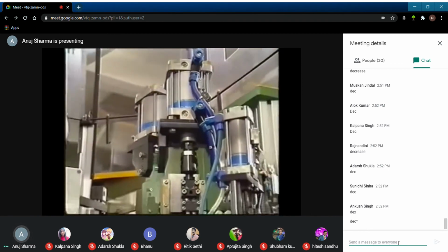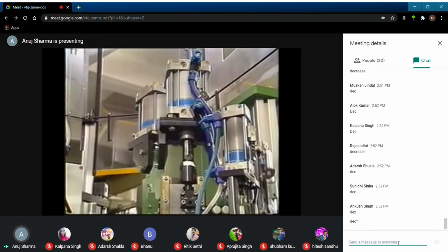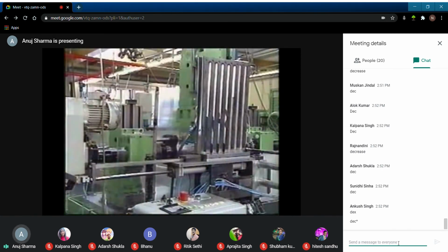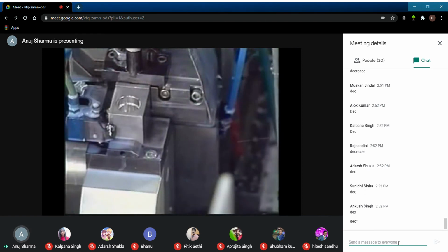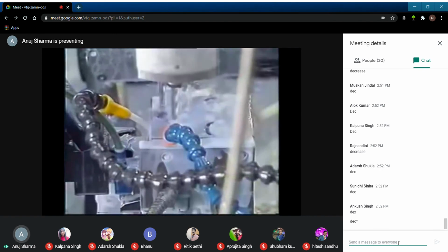The diameter of the piston directly affects the force, speed, and air consumption of the cylinder. The most efficient design uses the smallest cylinder adequate for the application. In this machine, various size pistons are used based on the job to be done. For example, the movement of materials requires a different force than clamping or the movement of heavy tools.